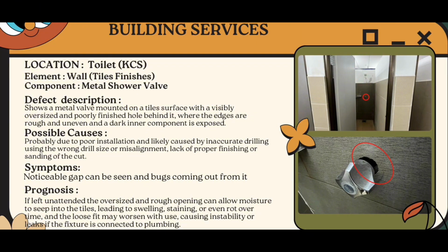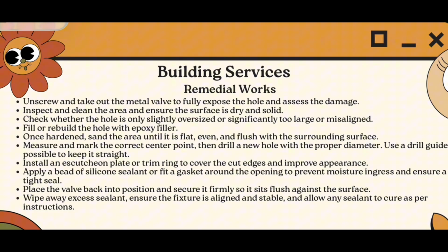The symptoms are the noticeable gap can be seen, and the prognosis is, if left unattended, the oversized and rough opening can allow moisture to seep into the tiles, leading to swelling, staining, or even rot over time. And the loose fit may worsen with use, causing instability or leaks if the fixture is connected to plumbing. And these are the remedial works that are suitable for the defect.